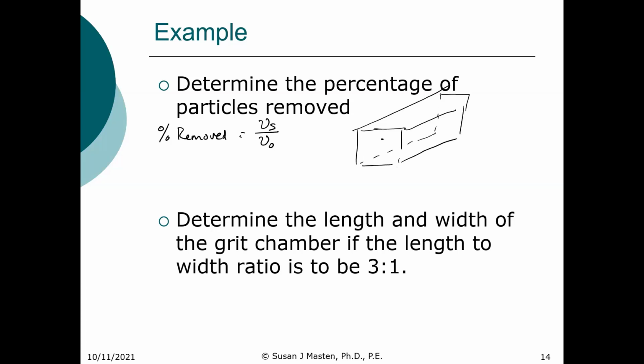okay, we have particles that come in at different velocities or different depths. So this particle here comes in and it's removed. This particle is also removed. However, this particle, same settling velocity, escapes. If this were an upflow, well, let's calculate this first.